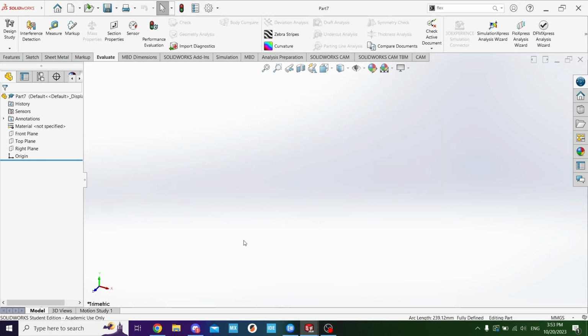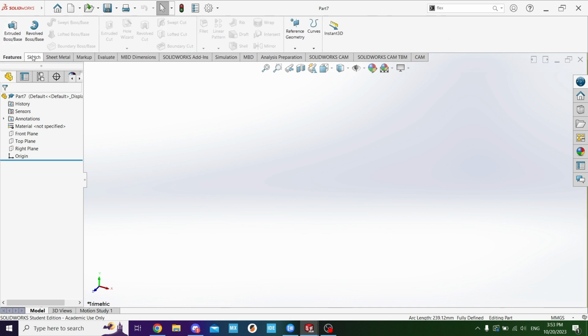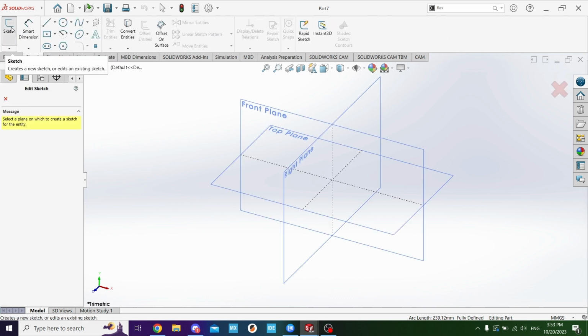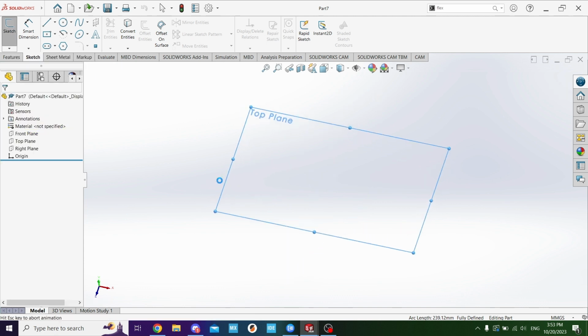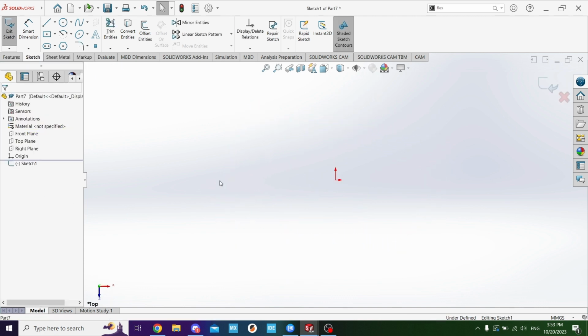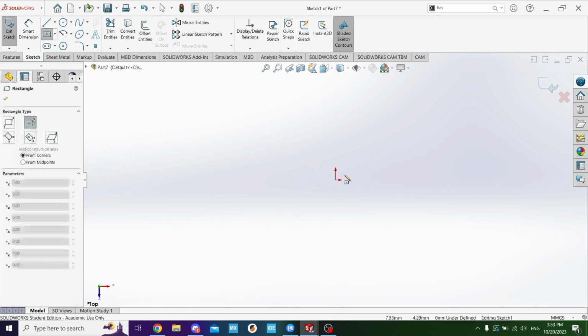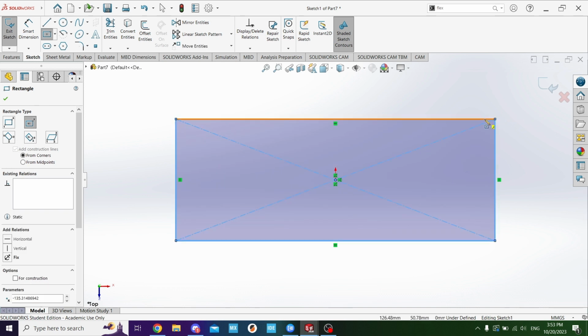How should we start? Square. Rectangle. Okay, not bad. Measure the physical piece. What plane? Top plane. Right, it doesn't matter, realistically. I was going to pick right. Anyways, rectangle. Let me just draw a quick, easy rectangle, right? Dimension.